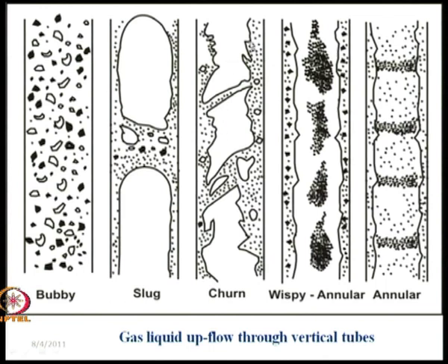Okay. So, therefore, from this chaotic and random churn flow pattern, we enter into the annular flow pattern. In the annular flow pattern, the gas forms a continuous gas core and the liquid is pushed towards the walls. It forms an annular film, just like the film which we had seen in the Taylor bubble region.